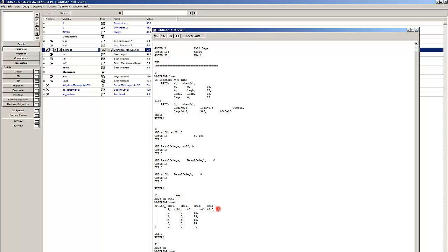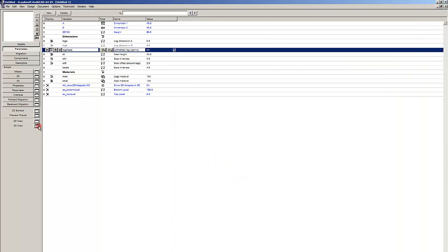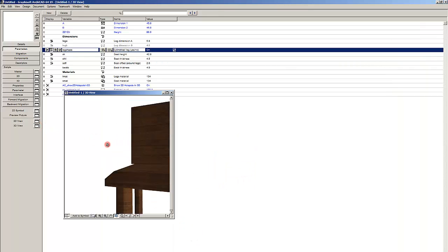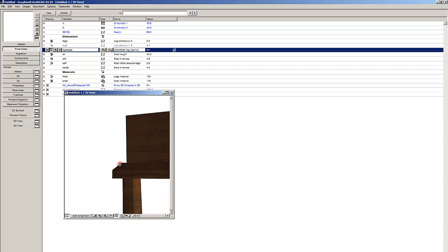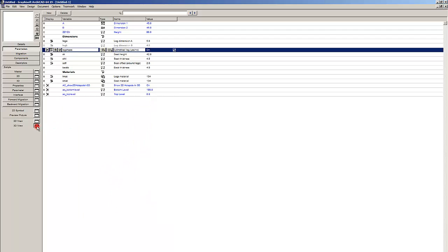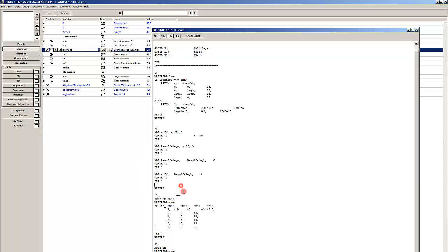If angle is 0 degrees, it will just fillet and not chamfer the ending. We have to type, of course, all commas. Alright, and let's see the result. And obviously it is chamfered by 45 degrees. If you want it to be different angle, we'll use 75 degrees.